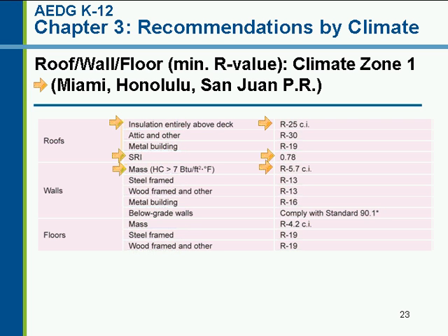And this calls for it to be continuous. That means it's uninterrupted by framing. So that means you've got it attached with some very small clips or something so that you don't have metal framing or even wood studs that are short-circuiting the insulation R value.